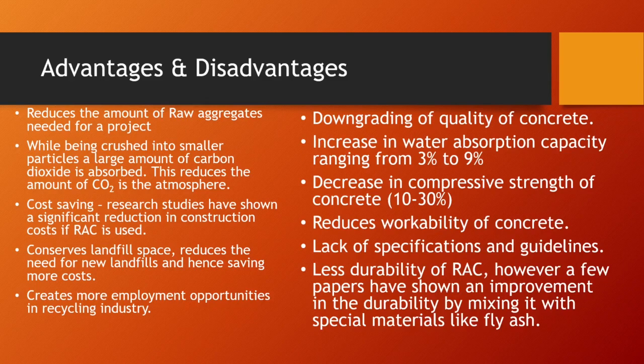When we're installing concrete fresh, when it's wet, it has huge workability. Once it's gone off and broken up into hard little bits, there's not much workability there. There's a lack of specifications and guidelines, so it's very difficult to determine the strength of the concrete when it's all broken up like that. And there's less durability of RAC.